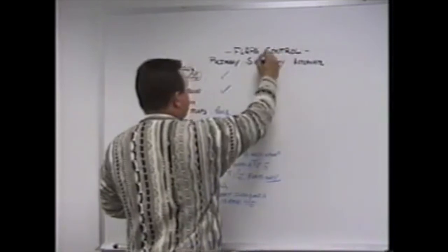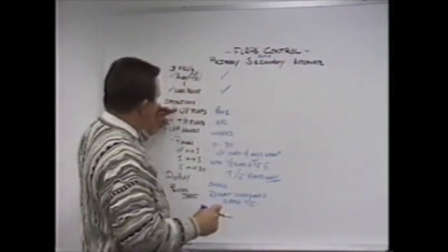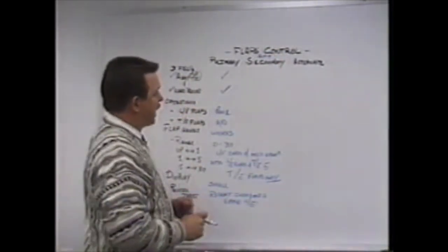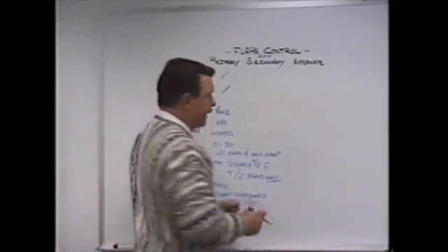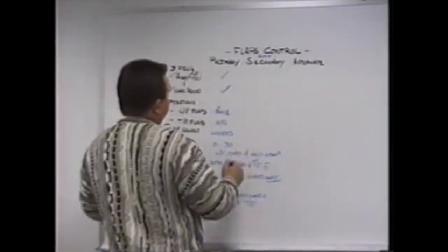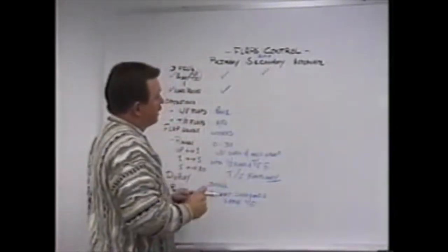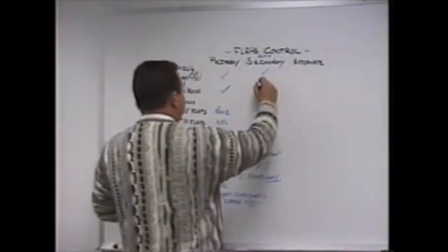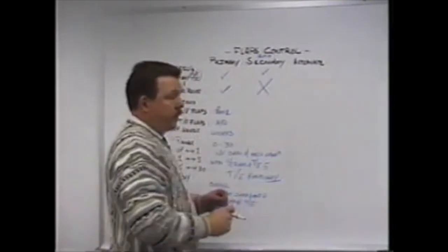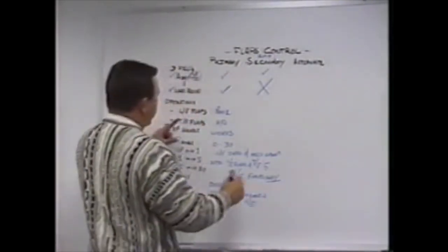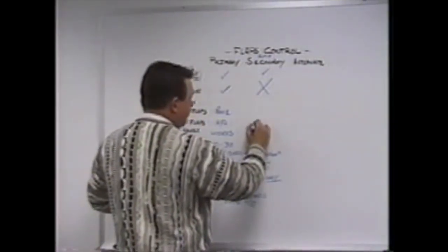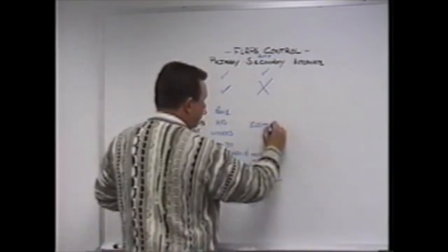If you encounter a problem with the leading edge pneumatic or trailing edge hydraulic flap drives, the secondary function will automatically kick in. The 3 flap control units still work. You do have symmetry protection on the leaders and the trailers in the secondary mode. However, you do not have load relief, because the source of power to operate the trailing edge flaps in the secondary mode is electric motors.